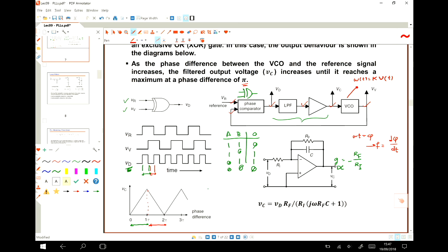Okay? So when the system starts up, we have to push our VCO to the point that we can ensure that, okay, it's going to get locked. I mean, if your carrier frequency is 900 megahertz, definitely if your VCO is running at 600 megahertz, it's not going to get locked. But if your VCO is running at 898, then it can get locked to 900 megahertz.